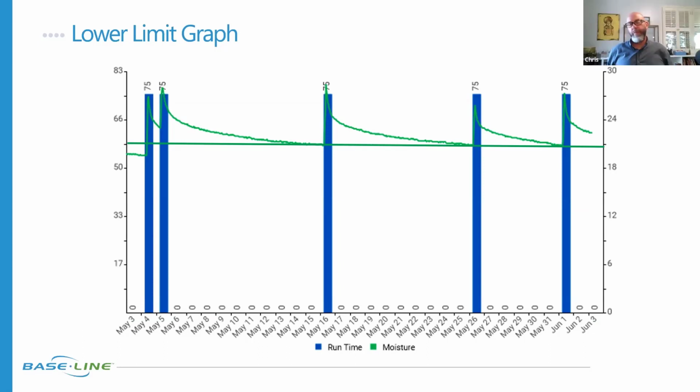So would you be using water budget while you're using soil moisture sensors? You could. It just may need to water more. If you had it at 50%, it'll just run more frequently because you're not applying as much water.